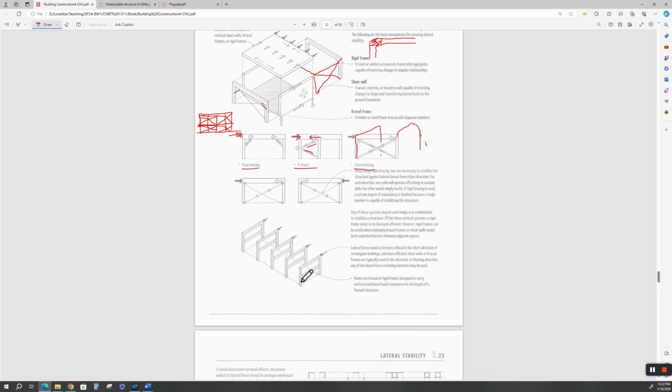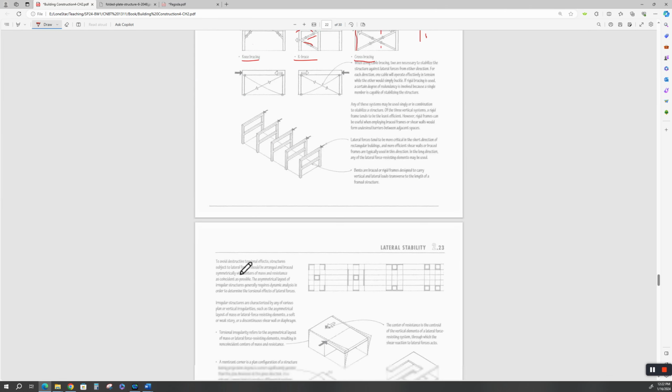Maybe your calculations, your K-bracing will take it 1, 2 bays, and maybe this bay needs to have a traditional shear wall. Maybe, who knows? Or some more substantial bracing. But you and your engineer will figure that out. Now, if you're doing a prefab metal building from a company that has designed all of this, their structural engineers already have this computer modeled and will be able to guide you on what you need to do.